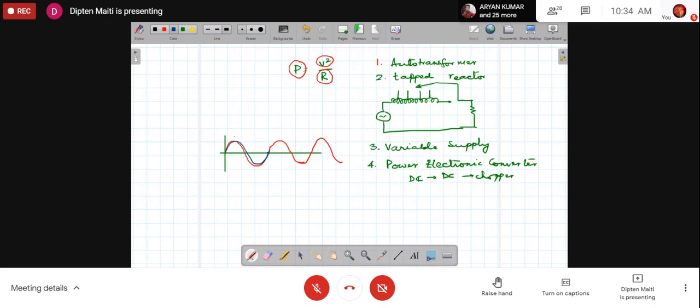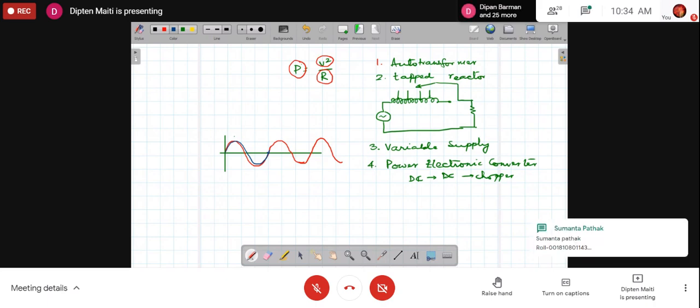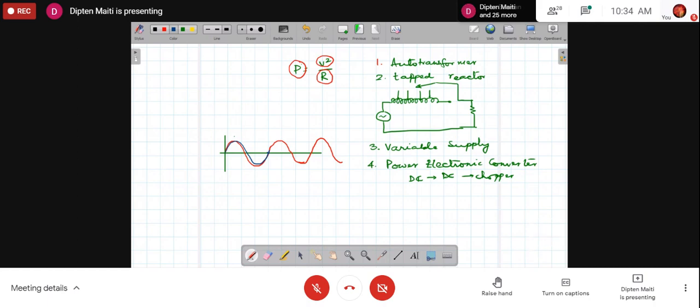Now, once that is put in operation, it attains heat up to the rated point, so that the resistance becomes its rated value. There, the current itself would be limited by the resistance. However, at starting, the current may become very high because the resistance would be around 1 by 10 of the rated value. So if you suddenly turn on the current through the resistance, the current may be around 10 times larger.